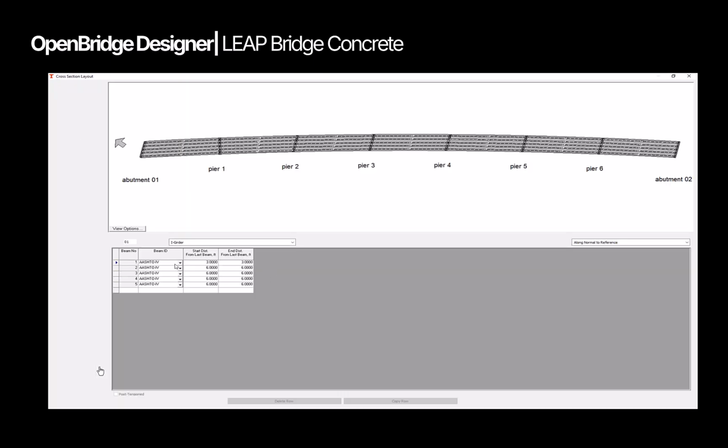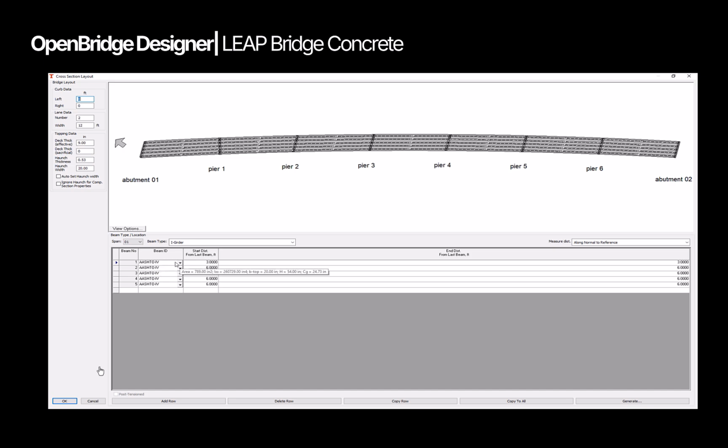So the next step after that will be not only to, we can change, for example, maybe we need to change the beam size. So just to illustrate the concept, changing the beam size in the analytical solution, right? But I want this change that I made to be carried over to the 3D model. Actually, the 3D model, the beam model, is the single source of truth, as we call it. This is the repository of all the information, not the analytics. The analytics is just, let's call it, our calculator, so to say, right?